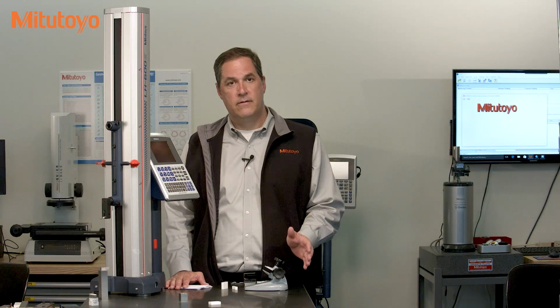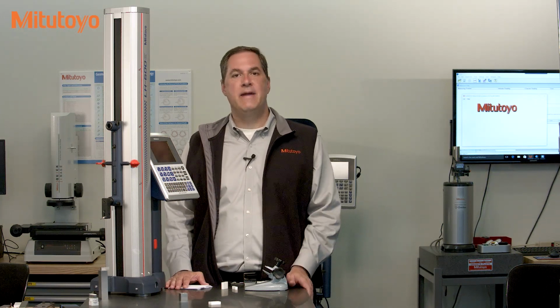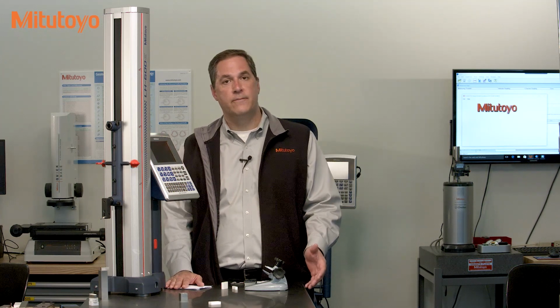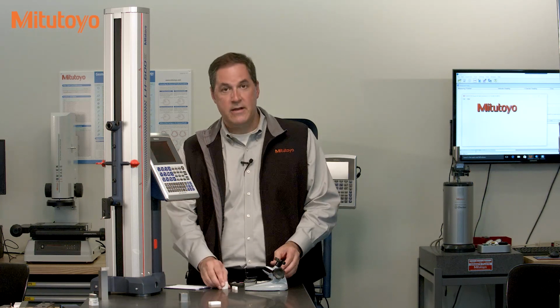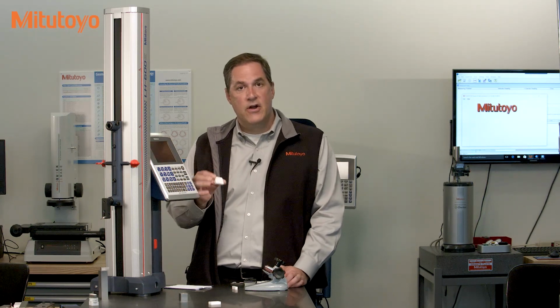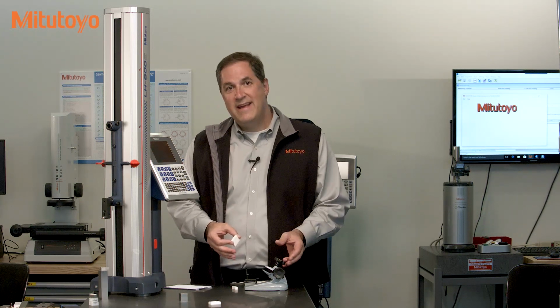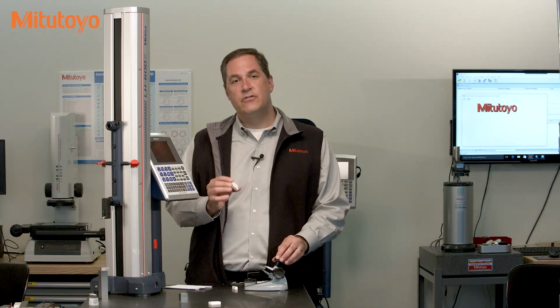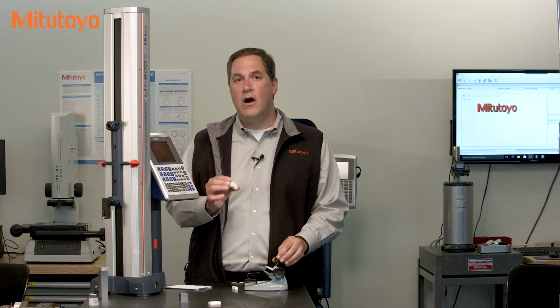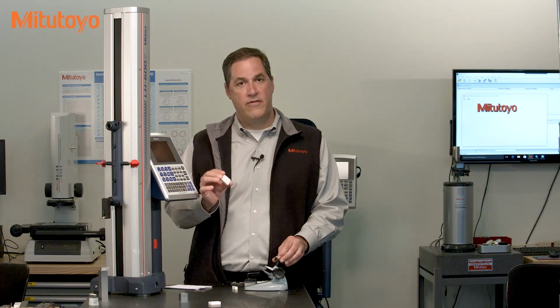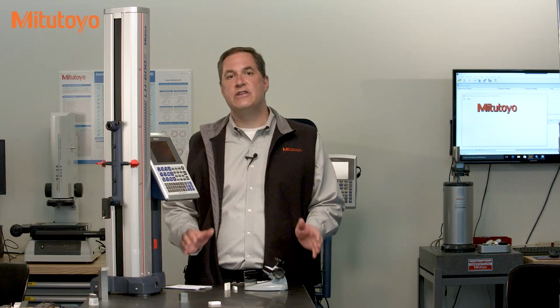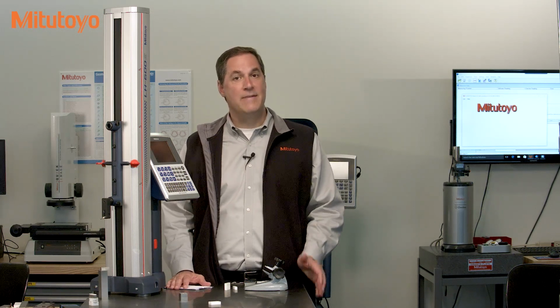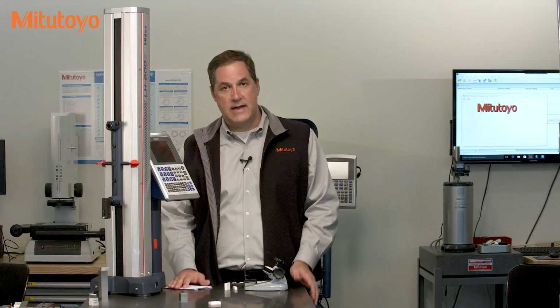or larger. And the default rule in many of the ASME B89 standards is a TUR of 4 or larger. And the reason we recommended grade 0 gauge blocks for the micrometer calibration is that you should likely be able to achieve a TUR of 4 or larger with them. Now, the reality is that achieving a TUR greater than 4 can be difficult or impossible at times.